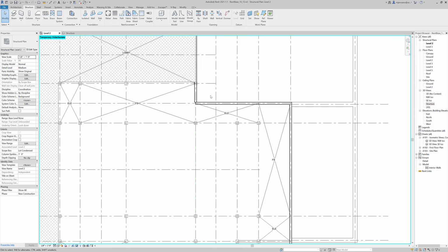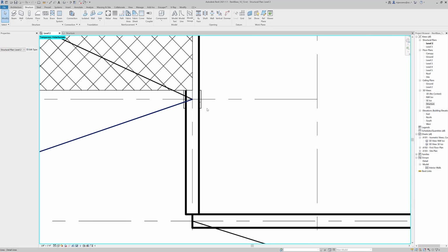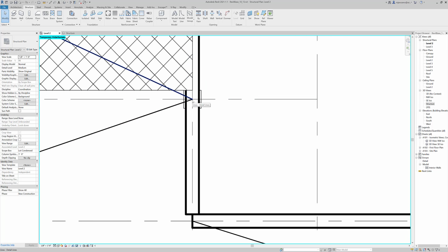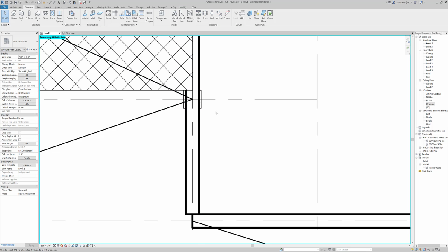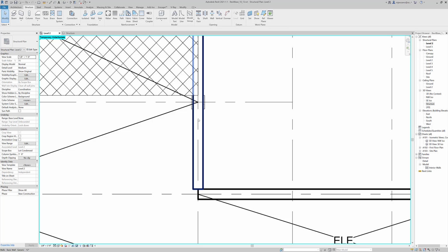Now the last thing I'll note here is sometimes you'll get weird intersections with your walls if you've developed the envelope. What I would recommend is taking your envelope and actually aligning it to the outside of your column so that your grid doesn't have to be redrawn and recreated. We're essentially adjusting our architecture to the structure because structure is paramount for this class rather than the architectural envelope. We can sort of fudge that stuff into place later.